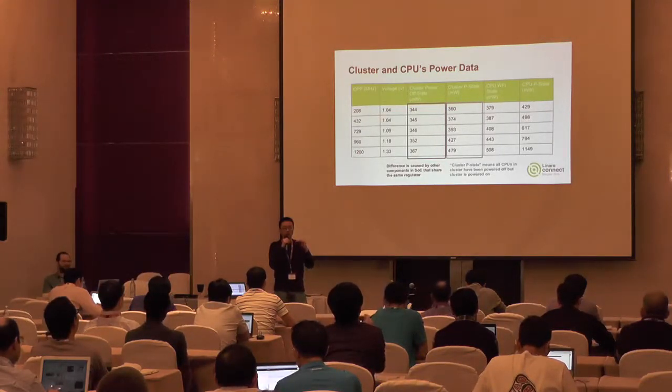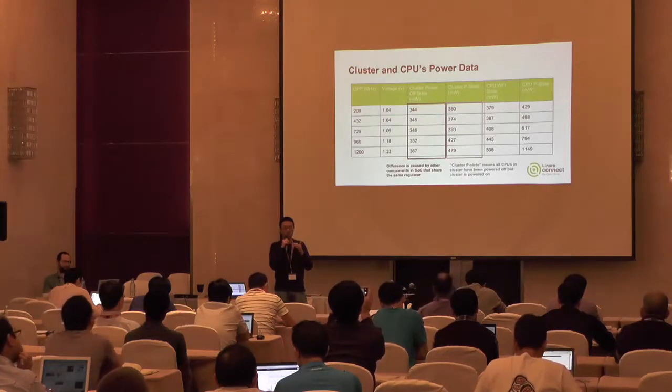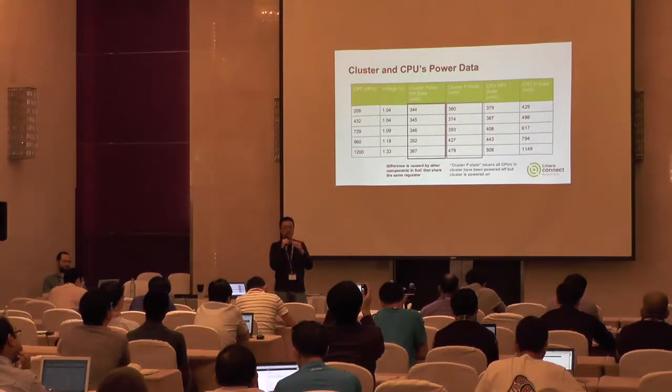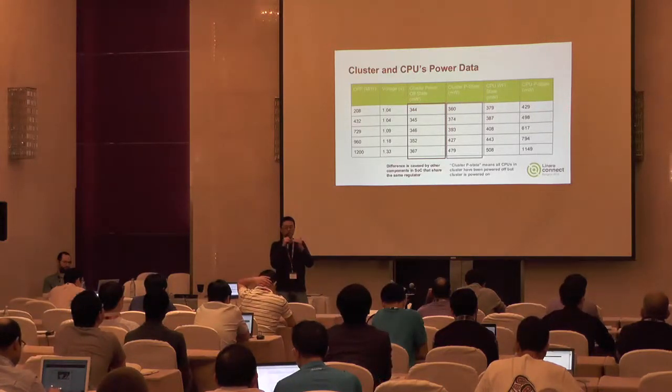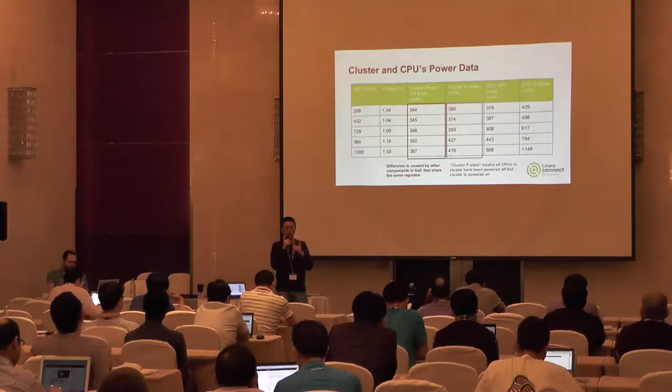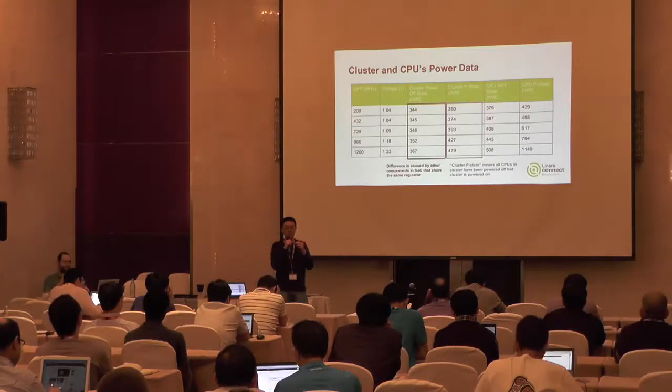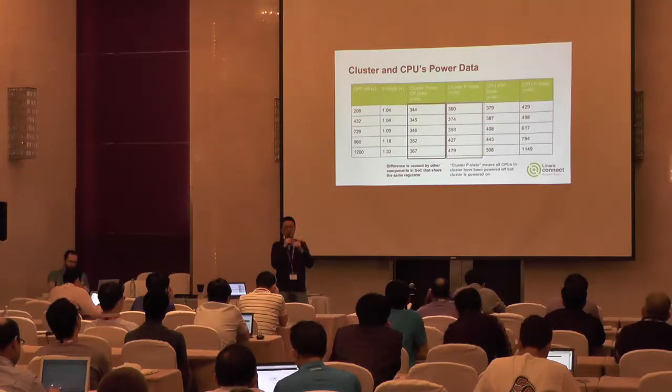Even if the voltage is different, it will not introduce any different power data, because internally in the SoC, the two clusters have been powered off. So that means the two clusters have no static leakage and no dynamic power. So whatever the outside voltage change, internally they will not introduce any difference.